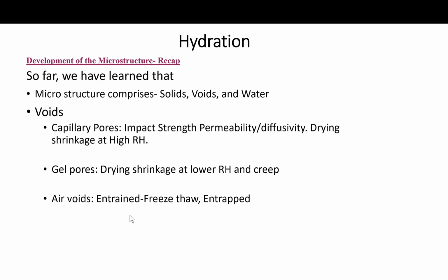Again, just to repeat, the capillary pores have an impact on strength and permeability. Then we have the air voids, which are the entrained air we intentionally add to the concrete for freeze-thaw resistance, and we have the entrapped air.